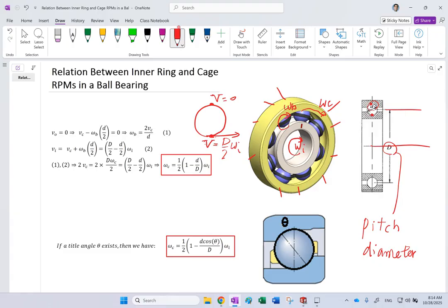And if that's the case, and this object is going with omega of the ball, and this is d over 2, right? And d over 2, then writing a simple kinematics relation would tell you the velocity of one side of it, that is 0, the other one is this. You can find the omega of the B. Omega of the B is going to be the difference between these two velocities divided by the distance.